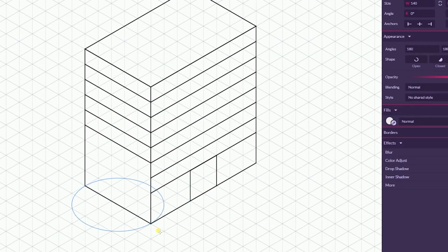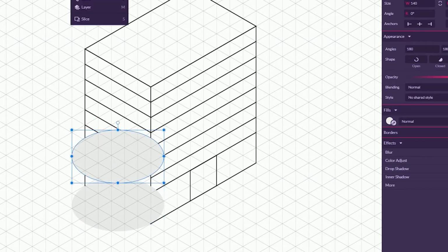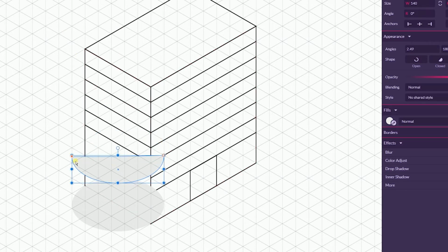Now we reach some interesting part of our tutorial, how to create this curvy line. I will show you a couple of tactics. First of all, we can place a circle here, and this circle basically should snap, and then we can make another circle. And what you can do next is to grab the Subselect tool and slice a half of this circle.